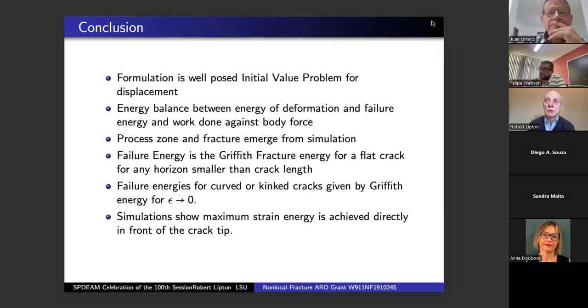Yeah. So you could have it done passively or actively. Actively, you would do it very much like this fellow seems to be doing, through the loading. You can figure out how to load your sample so as to guide the crack. That is the active way. The other, passive way is to put in heterogeneity at various points to influence the elastic field in the body. Once you have an elastic field, you can then interact with the crack.